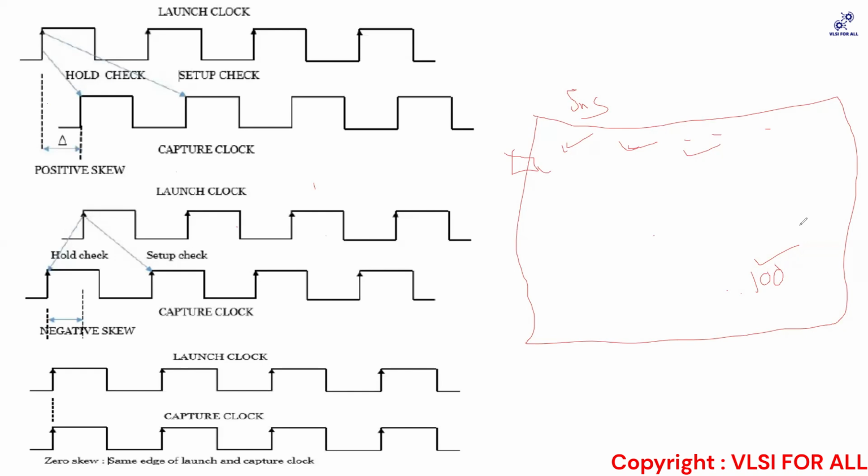Ma'am, but that is the goal of the CTS, no, ma'am? The goal of CTS, if you would have ever looked at it, is never to say that you should have 0 skew. You would have looked at it as a minimal skew. Correct? Because in reality, even in the real world, it is impossible to achieve this. If you look from the industrial perspective, there is no skew which is hitting 0 ns. That's why in the real world it will have either a positive skew or a negative skew. We set a target to minimize the skew. We don't want a huge difference in the skew.